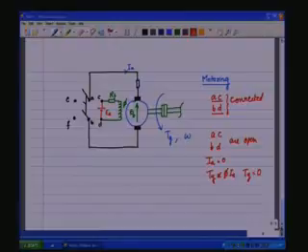So, we just allow it to gradually die down, there is no torque applied. So, on its own, because of the frictions associated in the bearings and so on and so forth, the shaft will coast and gradually come to 0. Now, that may take quite a long time depending upon the amount of inertia which is there on the shaft. That is called coasting mode.